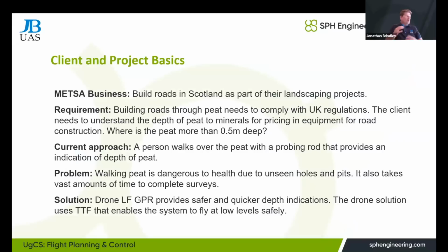So I had said a little bit about what Metsa do. They are building roads through peat. As we'll see in a minute, they are in Scotland, but they're building roads through peats, and they need to comply with UK regulations. They need to be aware of peat depths. And they also need to understand from their own perspective that when they're going to build a road, they need to know how deep the peat is, because that will have a bearing on what kind of machinery they're going to need to actually build that road.